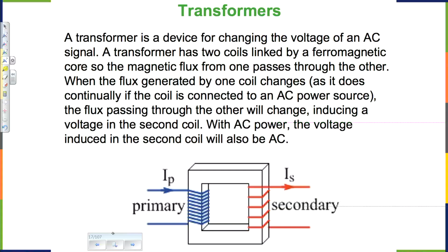Now I can measure the voltage across this coil, and I can measure the voltage across this coil. We can see this is close to 4. Now, this coil has 4 times more turns than this one. Of course, they have resistance, and of course, an ideal transformer doesn't exist. Ideally, we would read 16, 4 times 4, 16, but we read slightly lower number.